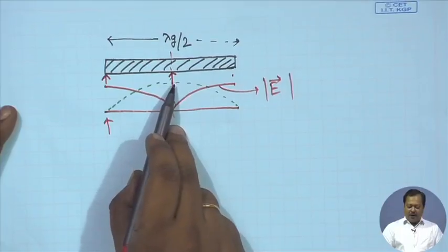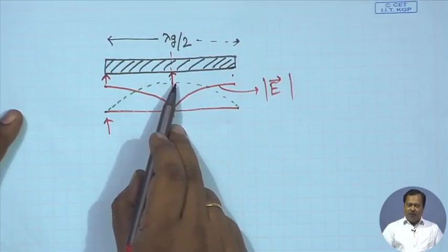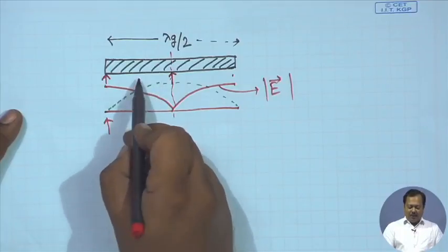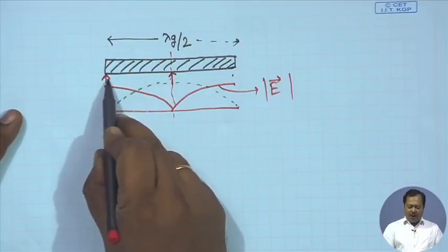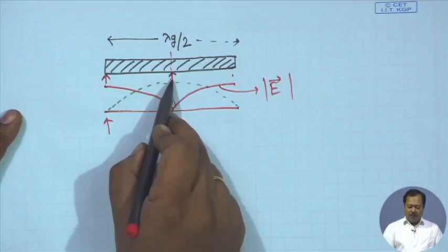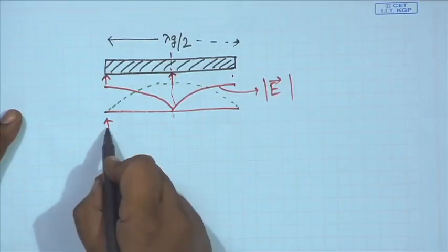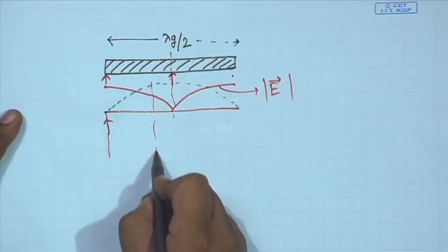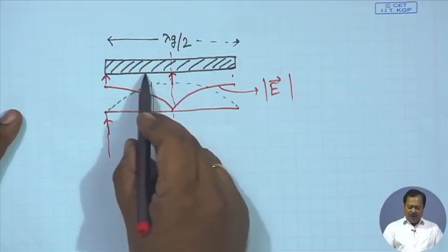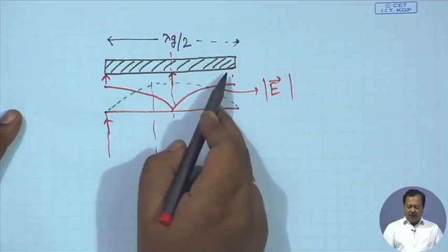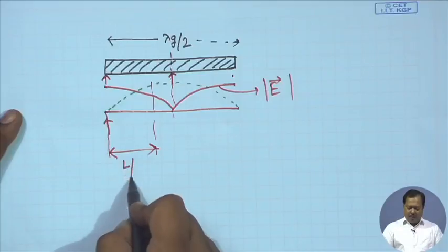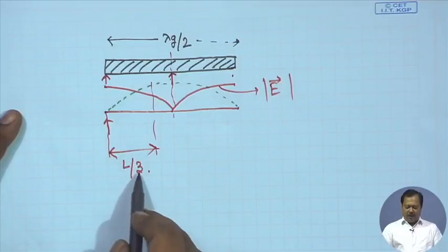For microwave circuits, mostly we use a 50 ohm system. So, for impedance matching, the feed point will be somewhere in between this z equal to infinity plane and z equal to 0 plane, and the thumb rule is that you consider 1/3 length from the left hand side. So, if the length of this resonator is L, then the approximate feed position from the left hand side is L by 3.